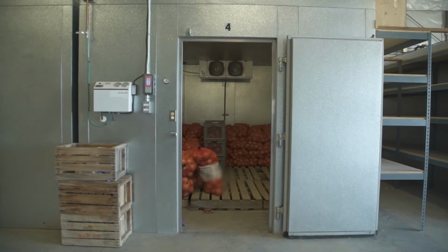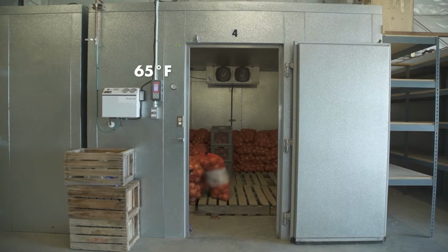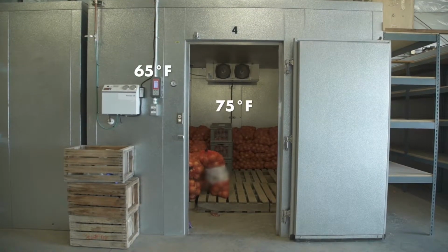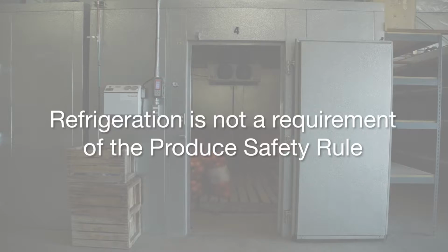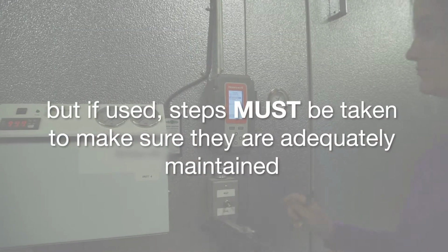For example, if your walk-in storage cooler thermometer displays a reading of 65 degrees Fahrenheit and the actual true temperature of the cooler is 75 degrees Fahrenheit, your thermometer is not very accurate. Refrigeration is not a requirement of the Produce Safety Rule, but if used, steps must be taken to ensure they are adequately maintained, and any instrument used to monitor temperature must be accurate and precise.